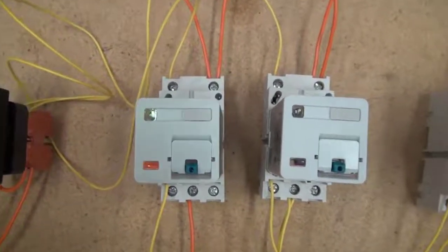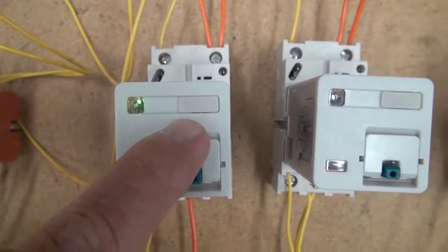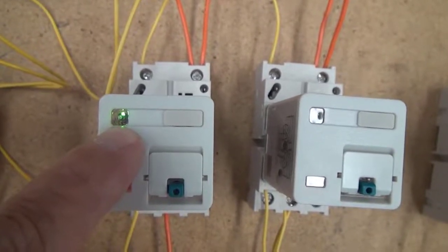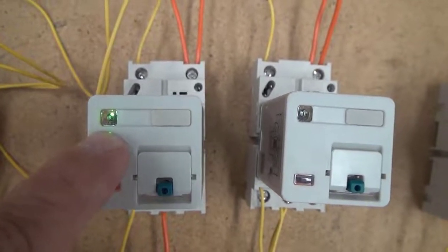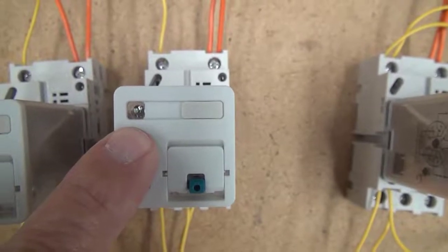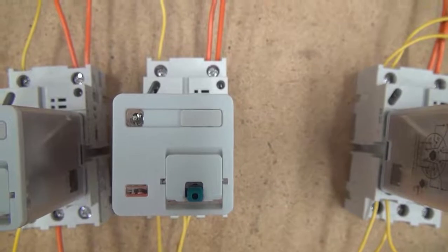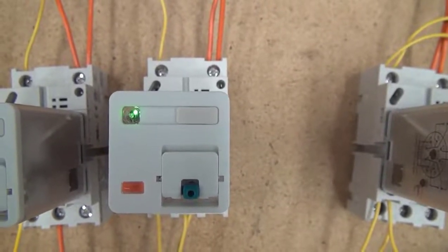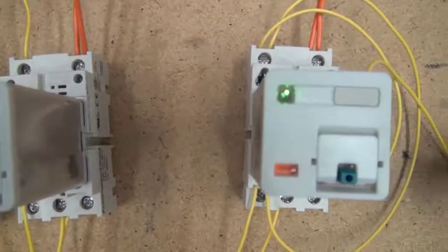You could see that this relay, I don't know if it might be difficult to see, the indicator is on so that the coil is energized, and it's energized because the stop push button is normally closed. This relay is the start contacts. It is not energized, but when I press and hold the start push button, you'll see that its LED turns on, which means it's energized. And when it's energized, this output comes on.